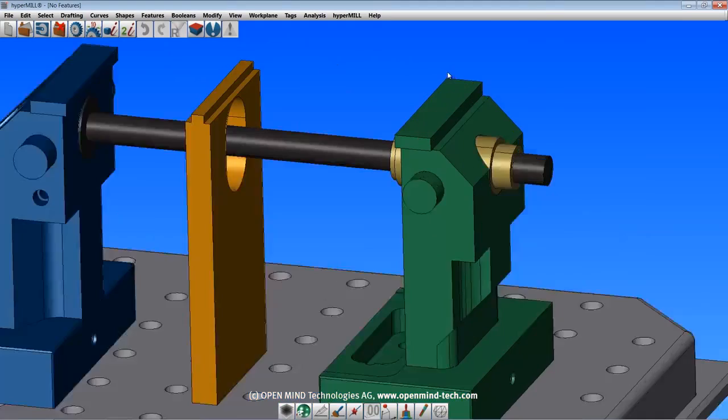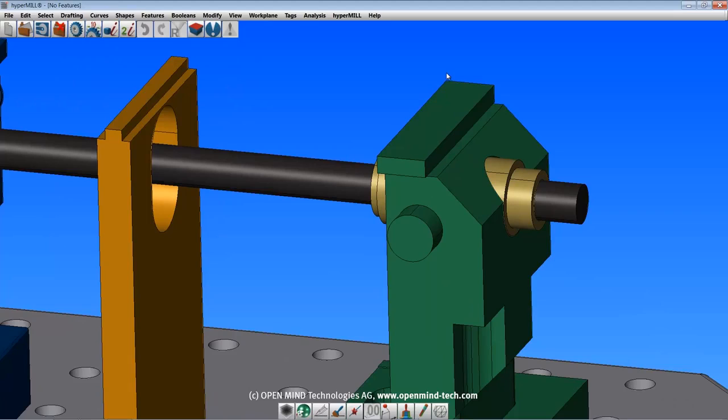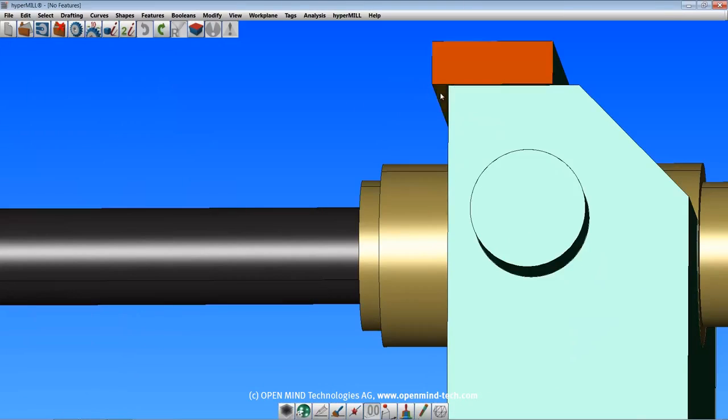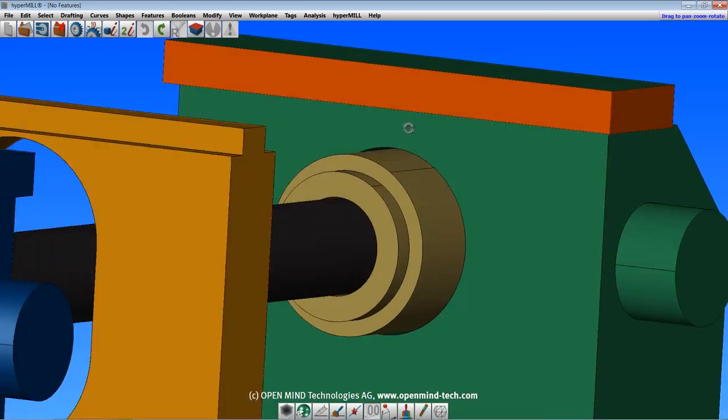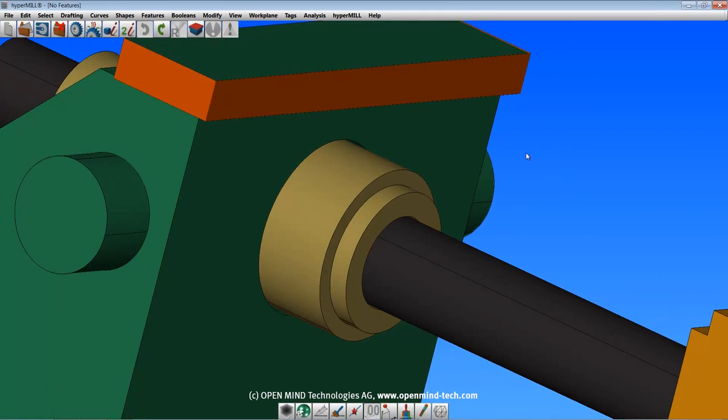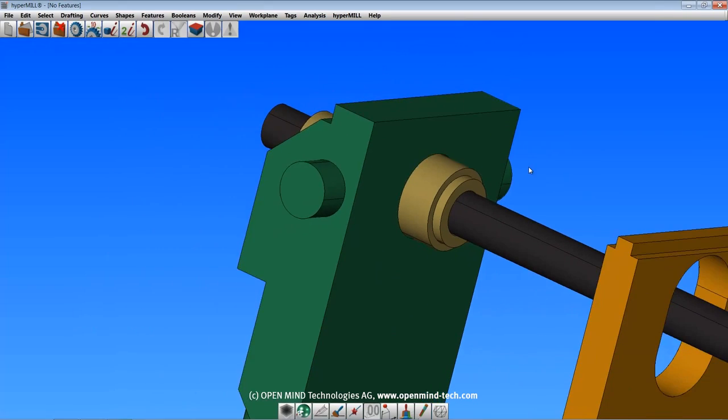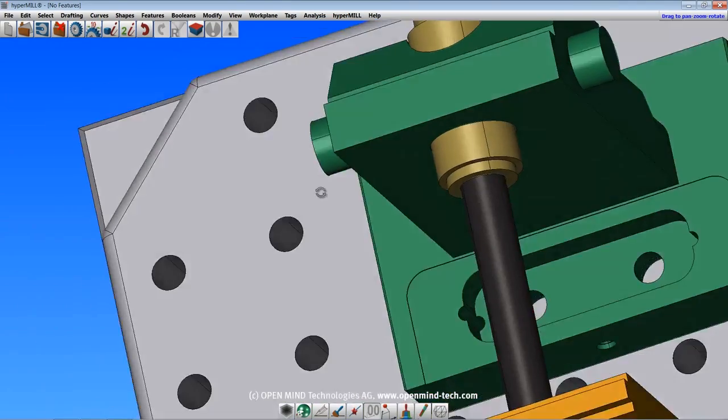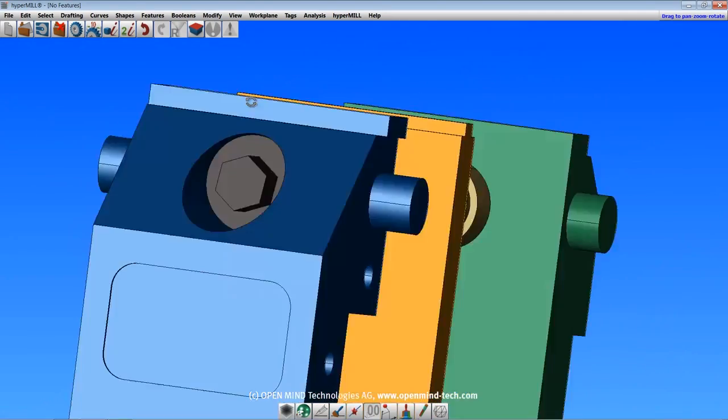Any surface in a solid model can be deleted, but in some cases you may be left with an open or non-manifold solid. For example, if I delete this top surface, I'll be left with an open solid. But if the remaining surfaces can meet at a new trimming intersection, the solid will remain closed. So if I delete the faces surrounding this block, the remaining faces are trimmed to their new intersections and the solid remains closed.